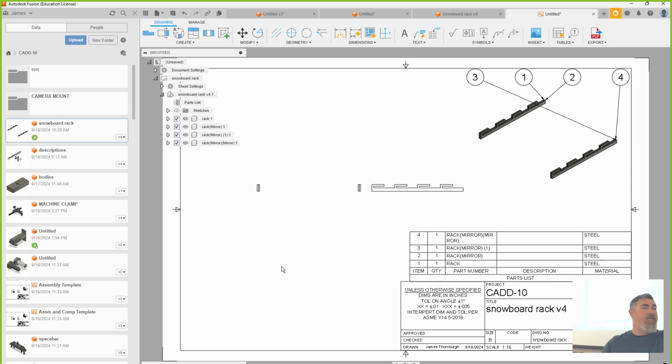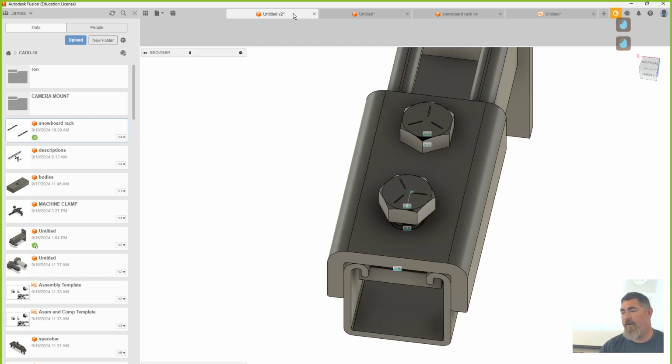So a lot of times, like something's going from this direction, you have another one in this direction. Don't do this one and then mirror it across. Do have 1 screw over here, mirror it to the other side. So now you have a different screw. You're not reusing the same one. Just use the copy or the duplicate with joints, right? Grab the other side. And sometimes when you do that, things go kind of wonky, right?